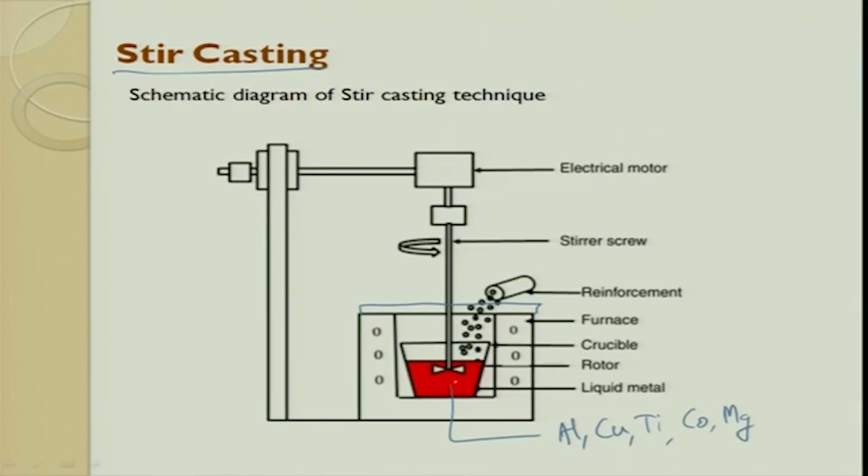Once it is melted, you use a stirrer, which is used for stirring and uniformly distributing the heat amongst the metal. So it does convection. This distributes the heat so that uniform melting happens all along, at a certain viscosity for which you have already done some experiments. You have figured out the right viscosity. Then you disperse the reinforcement into the metal.